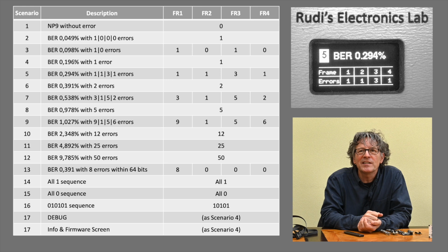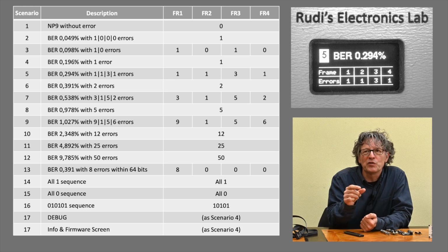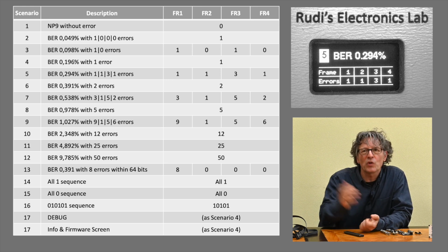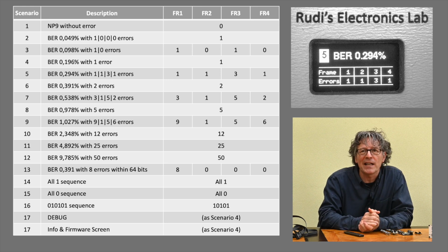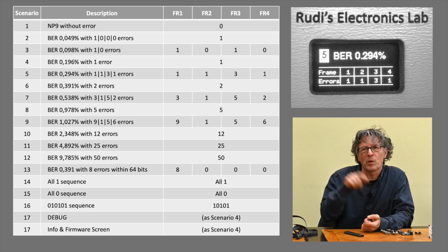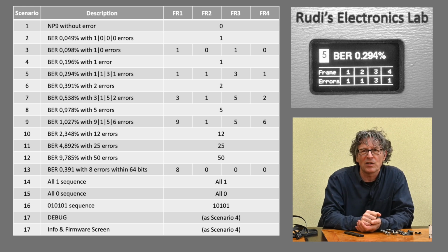So then we can really see how the microcontroller is waiting for the tick-tock clock signals, and if we have enough cycles there to properly relate to that, and whether the system that detects an error of too high an external clock signal properly informs the user that there's something wrong there.